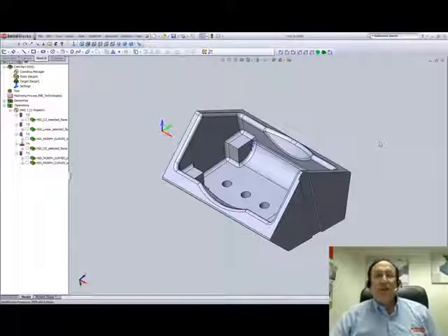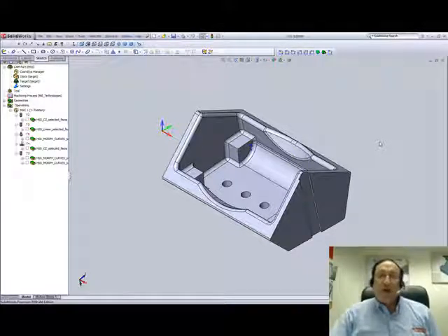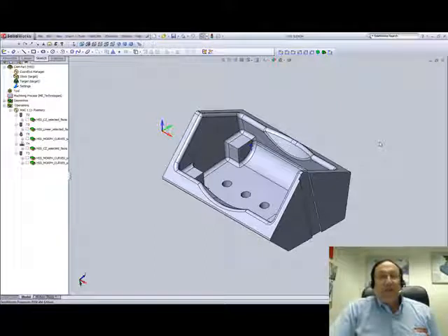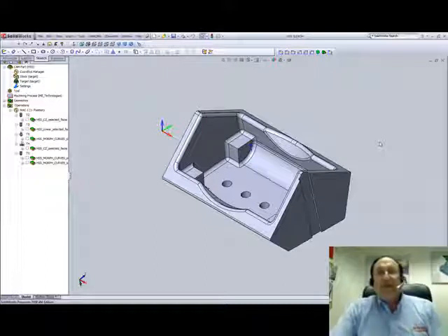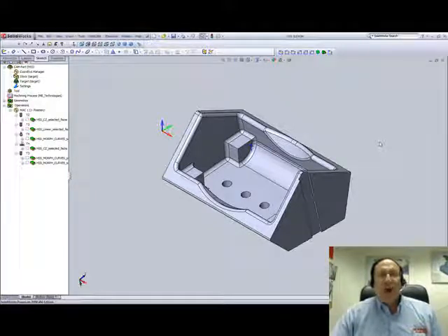We've seen in this demonstration on HSS some of the major advantages of using HSS on parts, whether it be for undercuts, for fillets around the part, or even on radiuses, or even flat floors or walls. It's a simple tool that can be used on any part, whether it be a 3D part or 2.5D part. You don't even have to be doing any kind of 3D machining. This is a perfect tool to get to any of those surfaces where you could not get to before, and it's done easily with a really nice, smooth toolpath.